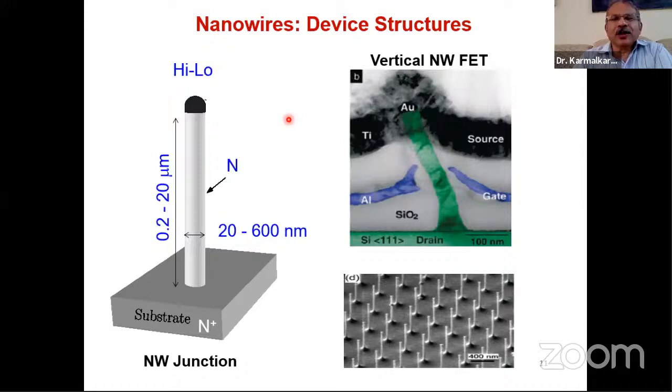So I have told you that first we are going to talk about nanowires and different types of contacts. That is what we have seen: end bonded contact, side bonded contact, depending on the nature of bonding. High-low, Schottky, PN contacts. These are also other types of contacts, right? Now, just now I mentioned PN. So this is an example of a PN junction. Part of this wire is P-type and the remaining part is N-type. Then it is a PN. Here you have high-low, this part.